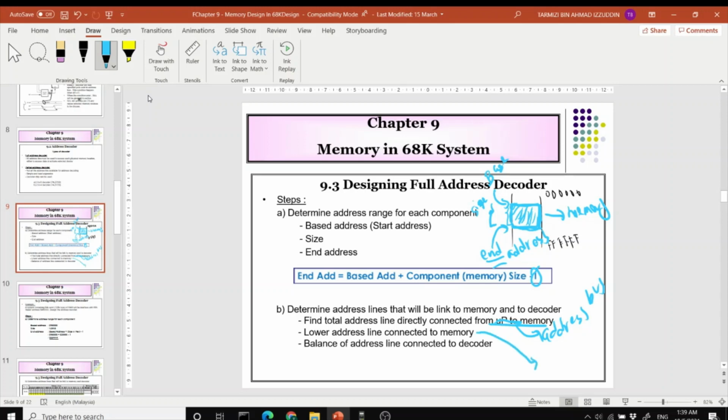Next you're going to see the UDS and LDS part, upper data strobe and lower data strobe, because later on, if you remember correctly, your address consists of an odd region and an even region. Depending on the lower address, which is A0, it will specify whether to write on the odd side or the even side.